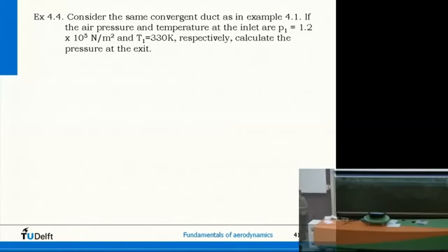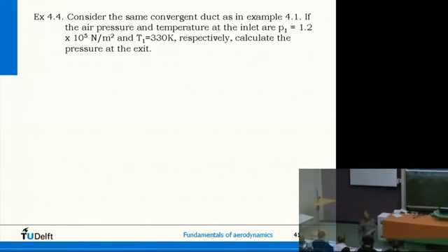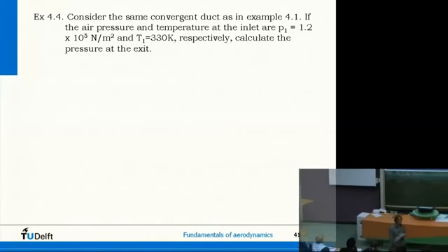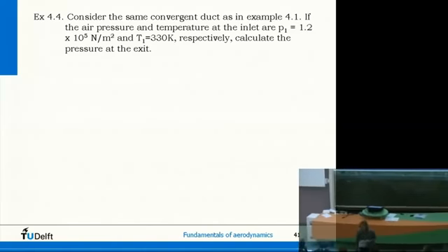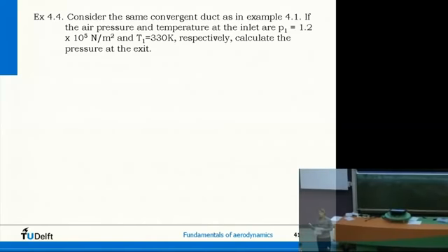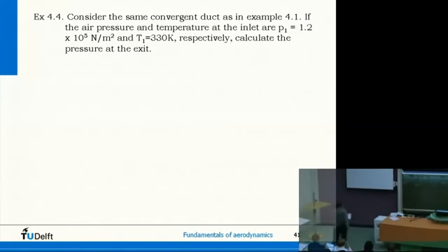So what relation can we use? Now it's sort of trivial. Later you will get more choices of relations. Relation to find the pressure. Any ideas? Bernoulli's law. Bernoulli's law, perfect. Very hard. But you should ask yourself, is Bernoulli's law valid? So can we apply it? Do we have low speed subsonic flow? Does anyone remember the maximum speed we had? 30 meters per second. Thanks. So yes, we can, right?